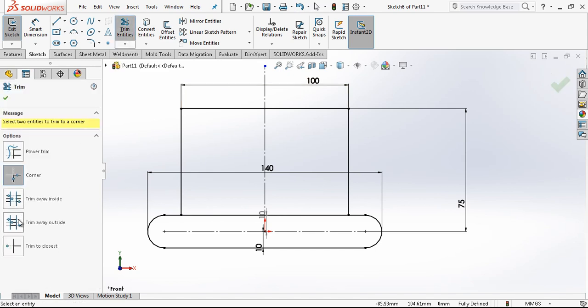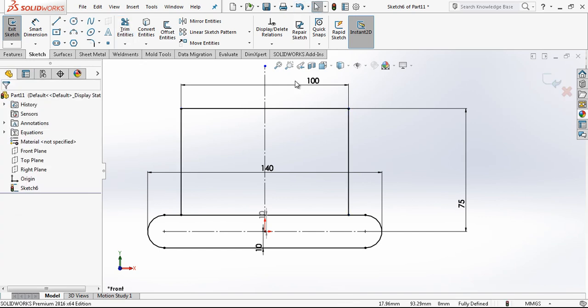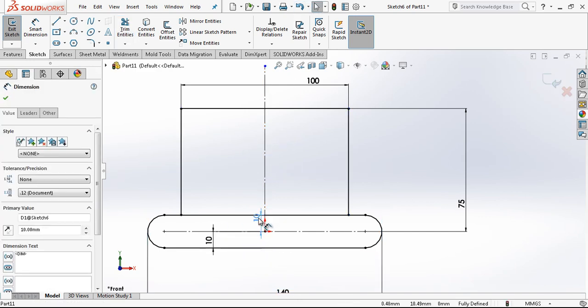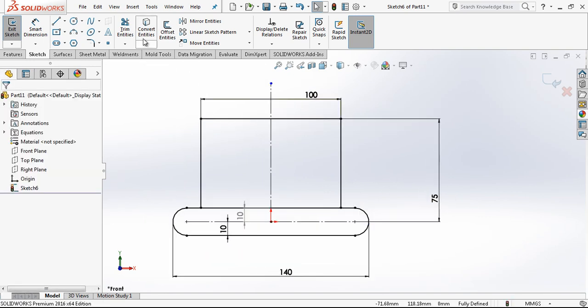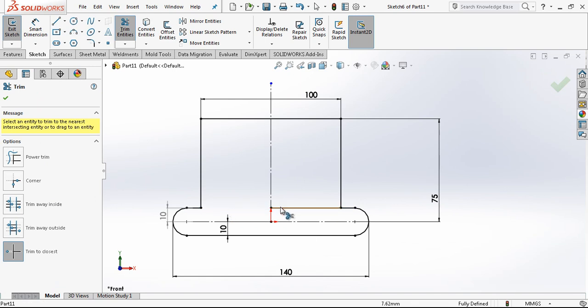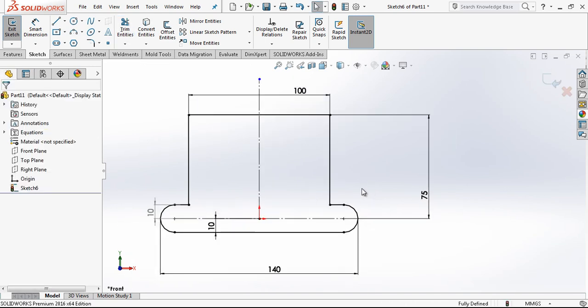These ones are used when you have many lines passing through the two areas. And this is also another way, by just clicking, like the old programs have. If you used AutoCAD before, you will recognize it simply. This is also another way of using these trim tools.